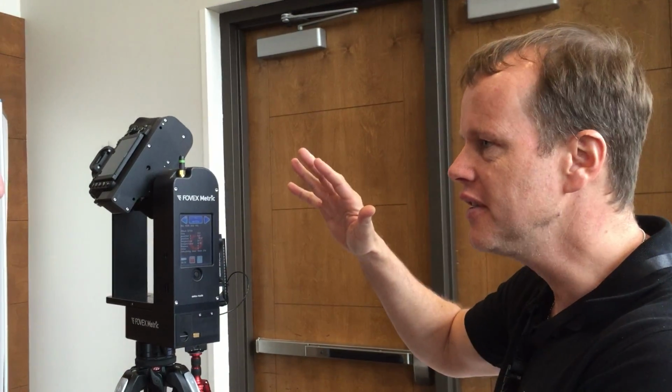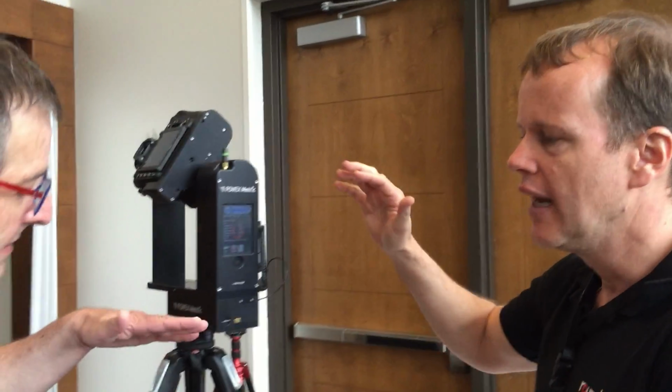Does the camera stay in one location, or does it move around the space? We create several images. Typically, one from this point, then I elevate the camera by maybe 30 centimeters, about 1 foot, do another one, and then go to several other stations to get a certain intersection angle to our objects, because we need this for the next step, the photogrammetry. So we need to create several.